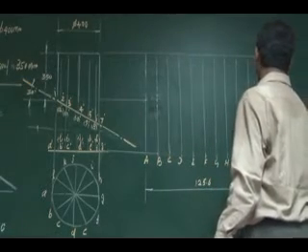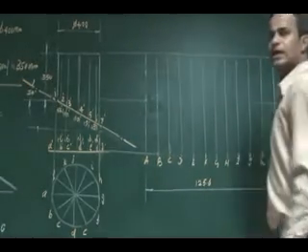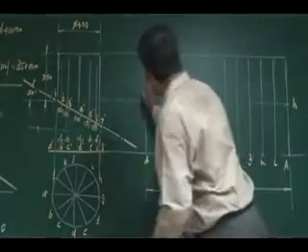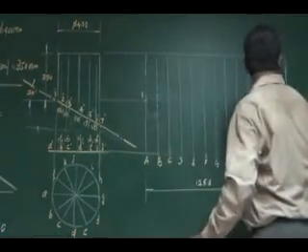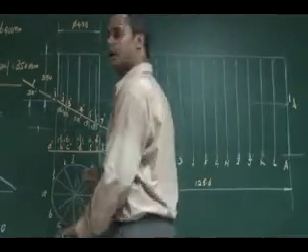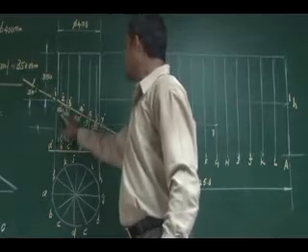So the same cutting point 1 will be projected to the generator, which will be at the end also. So the same A is available at the end also. So this is my cutting point 1. This is again my cutting point 1 in my development. So similarly cutting points 2 and 12.